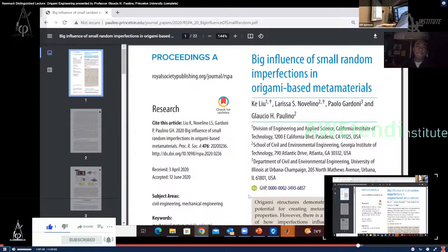Now, if I link that to the last part of the talk, you have this machine which is going to do 3D printing of that microstructure. So now your microstructure is done, and you have a very nice elegant analytical expression for positive or negative Poisson ratio. Now, I want to build a structure, a beam, on which I'm going to do a bending test. And that beam is made of the material that you're making out of your 3D printing.